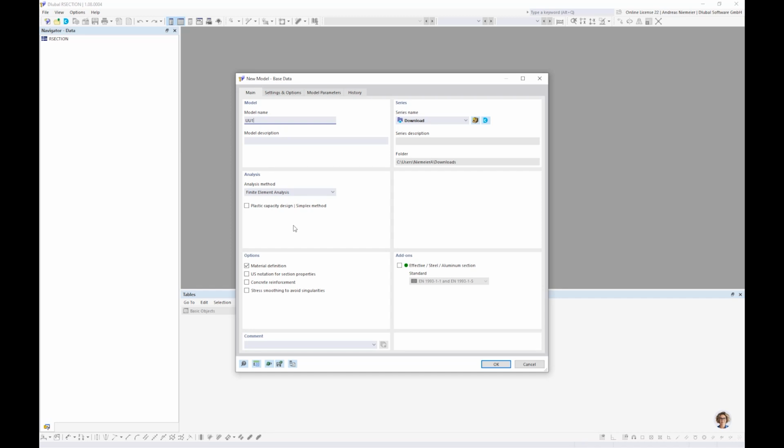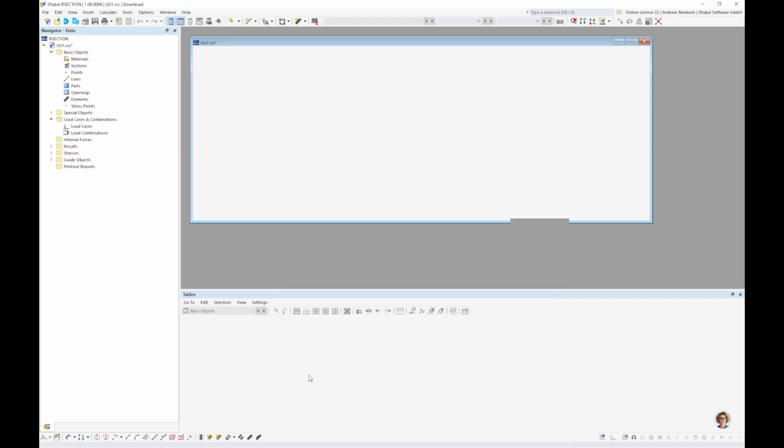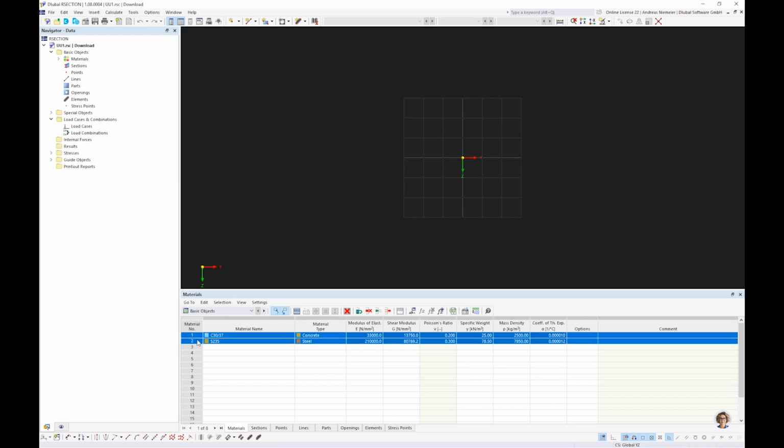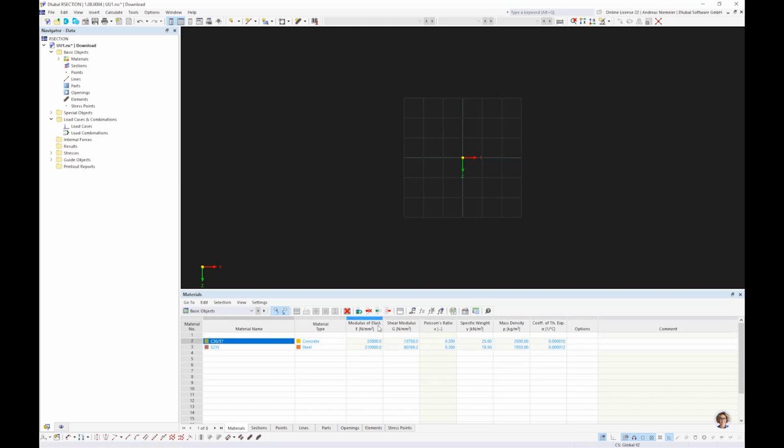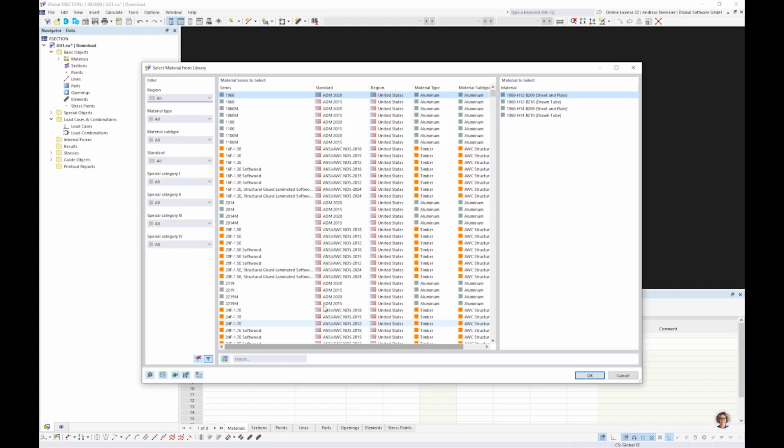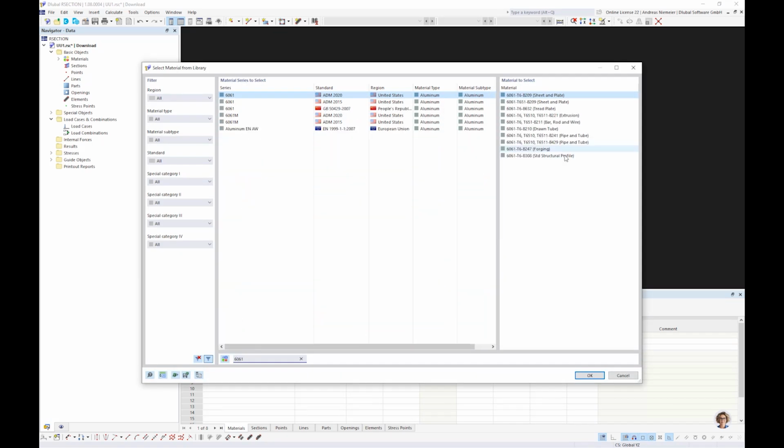And you know, in comparison to our old generation, in the old stage we had Shape-Thin and Shape-Massive, 2 programs. Now we have only 1, and you can decide here massive or thin-walled. Let's start with massive and create a user-defined section from aluminum which is extruded. For this I open it and specify the material, which means making a new row and writing here maybe from label 60, 61, and using such a T6 material.